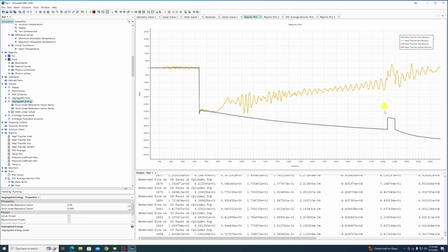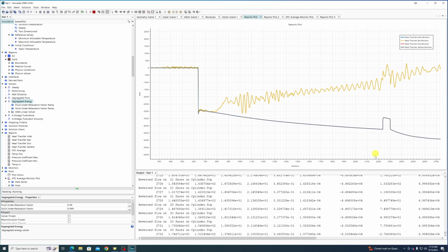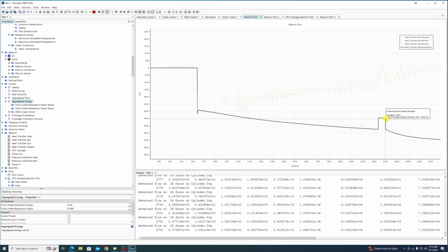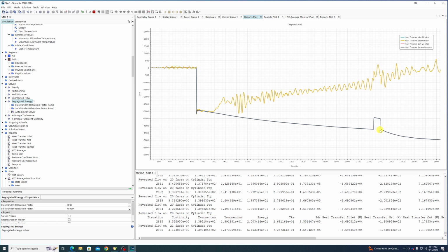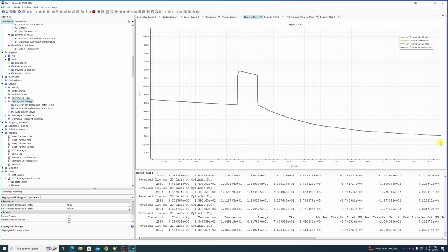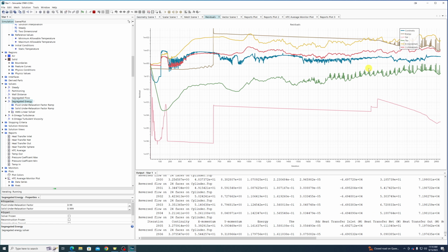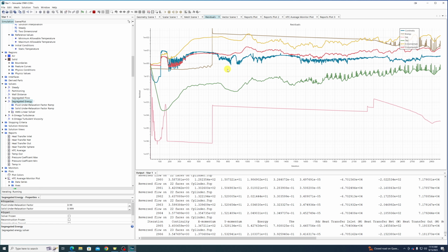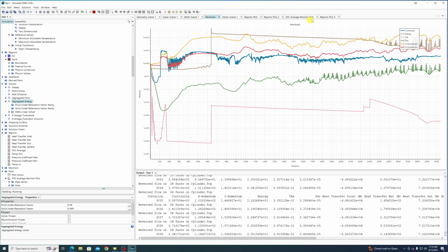So notice that this thing's out at a couple thousand iterations, even post this change. And it is nowhere near converging yet. This is very definitively, everything is still moving. We can even look at the residuals and see that they're pretty noisy. Natural convection, you're not going to get these residuals to come down very far because there's no forcing function.